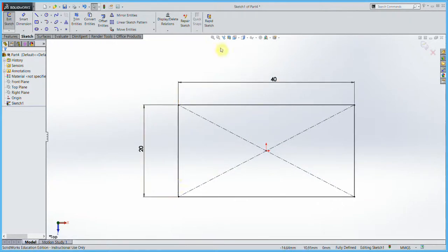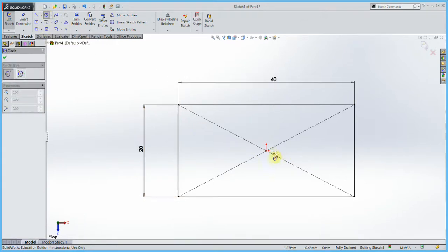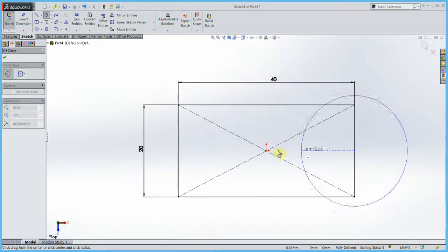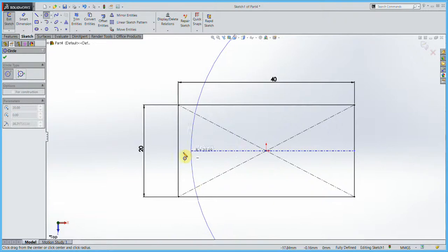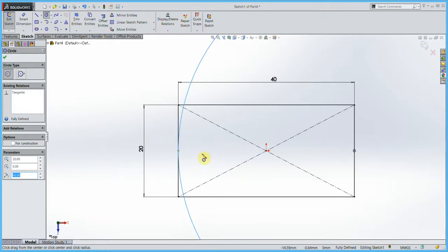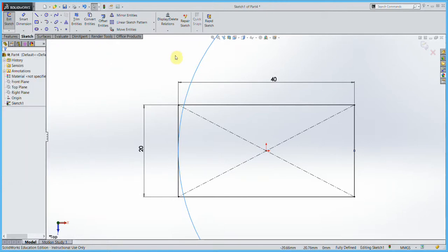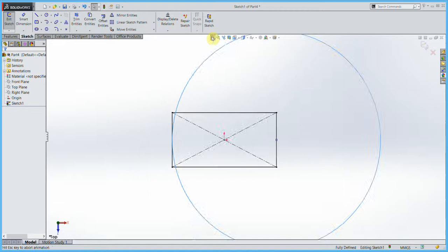We're going to make this end rounded a bit, so we go and get a circle tool. Now we're not going to start from here, we're going to start from this side here. Now when we go near the middle of this line, we get a little orange dot. We click there, and so that's going to be the center of our circle, and we're going to finish our circle over here. Now it snaps to this line as well, so let it snap and click again. Right, we finished drawing the circle, fit it on the screen again.